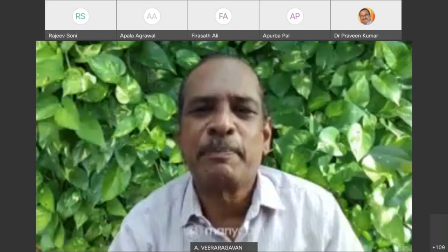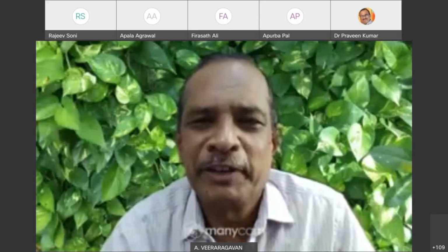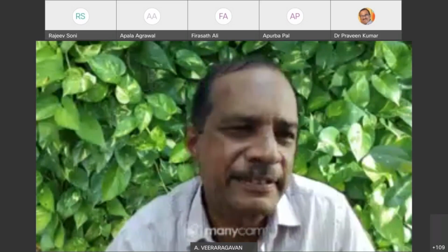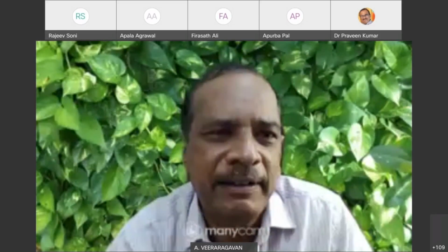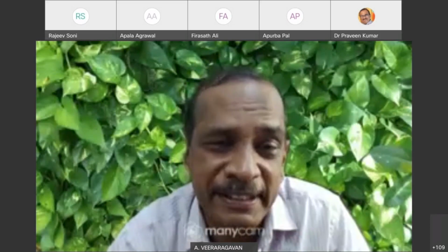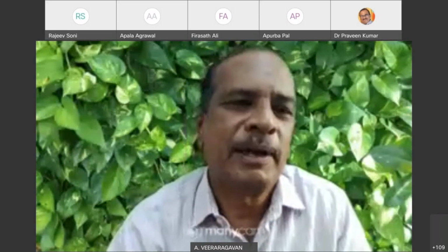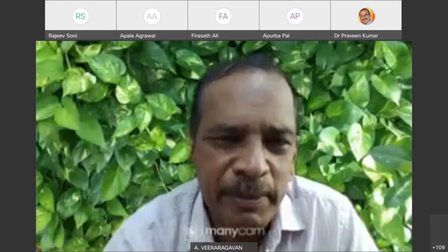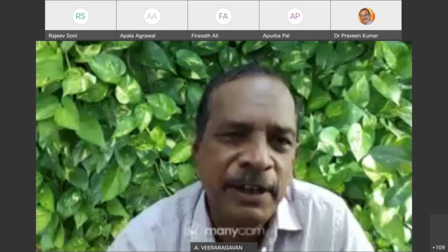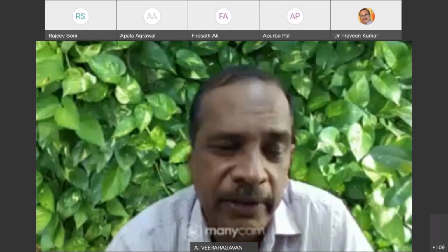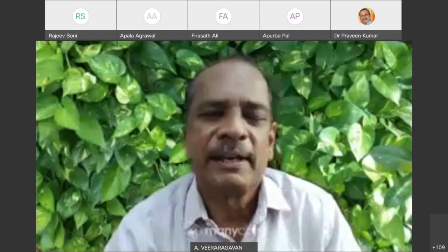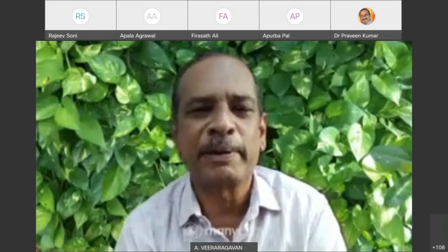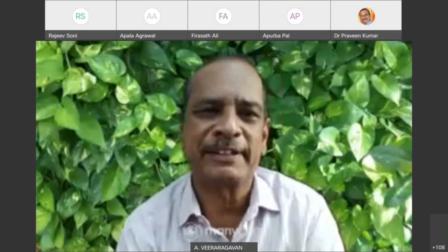I was thinking that he is asking about plastic and sustainability. Plastic is also another issue of environmental hazard which we are facing in the country. But what we have found successfully is that we are using waste plastics in bituminous layers. IRC has come out with a new code of practice in 2019, wherein we are able to make use of plastic in bituminous construction. We can take it, shred it, and use it in bituminous construction. The environment benefits by getting rid of the waste plastic. The road benefits because it extends the life, reduces moisture-induced damage, and therefore reduces the maintenance requirement. So I feel that plastic is a blessing in disguise. It is causing a problem, but on the other hand, I can improve the life of the pavement by using it in the bituminous layers.